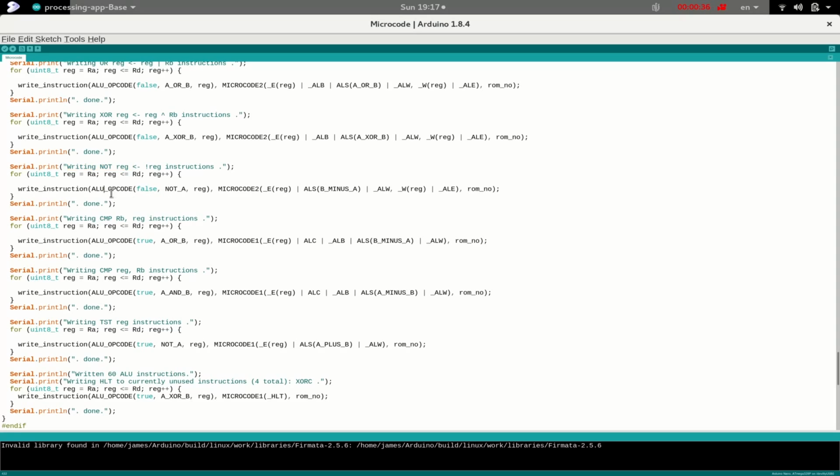And so the opcode which we'll use will be using this special combination of 3 bits, which is 1, 1, 1, which our ALU itself doesn't understand, but that's okay. We can use that in the opcode. And then to implement this instruction in the microcode, we'll just use this combination of inputs that we determined when we looked at the ALU. So we're using the B minus A operation. We're not setting the B input, so that will be 0, and we're not setting the carry, so we will borrow. And of course, it's a real operation where we want to write the result of the inversion back into the original register. And so we have our two steps of microcode: one to write the result of the calculation into the ALU register, and then another to read it out and write it into the final register.